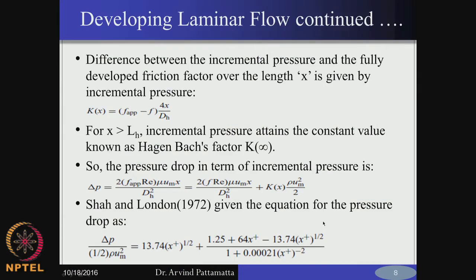So, we have looked into the aspects of liquid flows in mini and micro channels. The major difference from the macro channel flow case is that some of the effects like the developing length become very important for the liquid flow in micro channels, and therefore, when you are calculating, for example, the overall pressure drop, you should not jump into taking the fully developed condition and estimating the pressure drop.